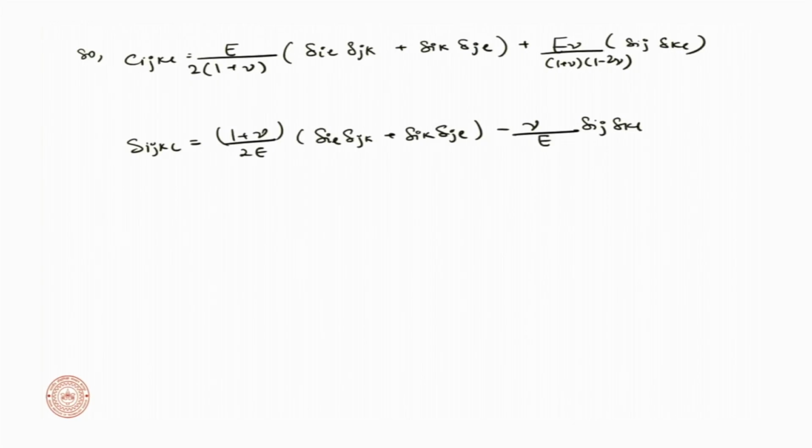With this we now have a definition of our stiffness and our compliance tensors. We can relate the stress to the strain. Then we will look into some reduced order models. Now, we have been doing everything in 3 dimensions, so the equations become very cumbersome. You have a lot of terms to consider, right? There are 6 stresses and 6 strains, and we are relating all of them with a 6 cross 6 matrix of material properties. Let us bring it down one dimension lower, and we are looking at a planar body.